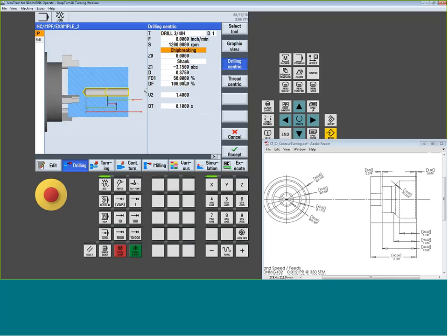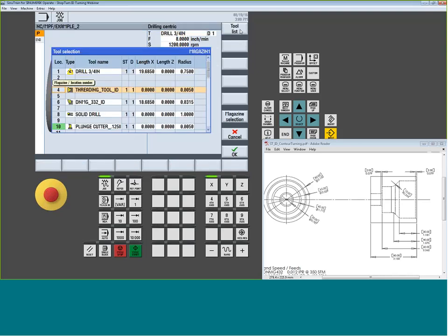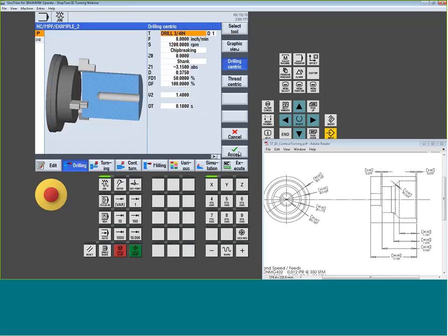Here it's time to start creating and picking our physical geometry. So first things first, I would certainly want to select my tool, and we had the 3/4 inch tool, and we do have a diameter called out on that. The diameter is really only going to give us a diameter for graphics purposes. Other than that, you're always working from the center of the drill on a centric type of scenario. So I don't need my diameter here, but I'm not going to see a drill hole if I don't have a diameter. So that's why I want to remember to plug it back in for the simulation.